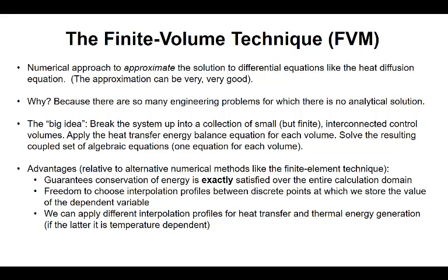Apply the heat transfer energy balance equation for each volume, and then solve the resulting coupled set of algebraic equations. There is one equation governing each volume that makes up the mesh, or the collection of volumes. In so doing, an approximation to the heat transfer in the domain is obtained.